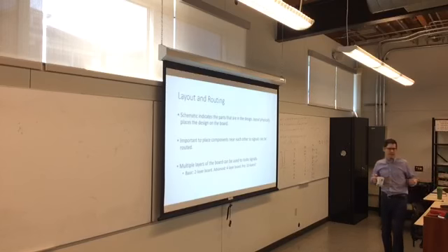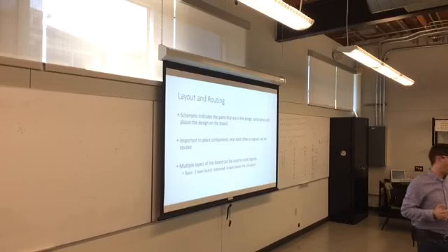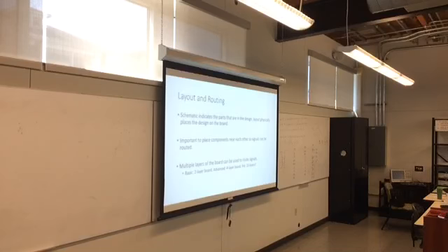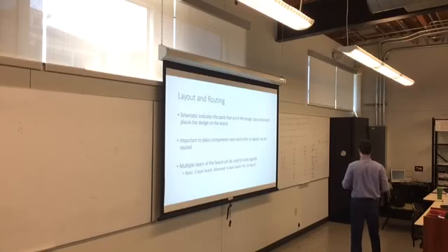It's important to make the design as small as reasonably possible for a couple of reasons. One, the bigger a board is, the more it costs. Generally a fab will charge you per area. So why make a 4-inch square board when you can just as easily make a 2-inch square board for half the price? But don't make it so small that you have to use tweezers and hold your breath while assembling it, because otherwise you'll misplace something. So make it small, but make it reasonably so.